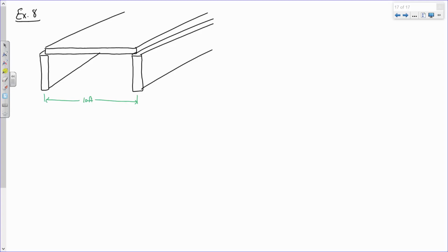So here are our beams, okay? Those are what we've been designing before, our 12-inch wide by whatever, 27-inch deep, with 4 number 7 rebar, whatever. Those are the regular old beams that we've been designing, but here's the slab that goes on top of them. And however far apart the beams are, that's our span length for the slab. Does that make sense? Okay.